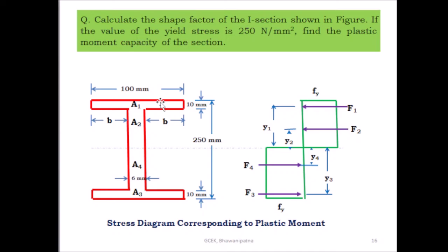So you know that is the parallel axis theorem. From the parallel axis theorem, you have to find out the moment of inertia about its own centroidal axis. Then you have to take the area into centroidal distance square. So here for this rectangle, about the self centroidal axis, what is the moment of inertia?